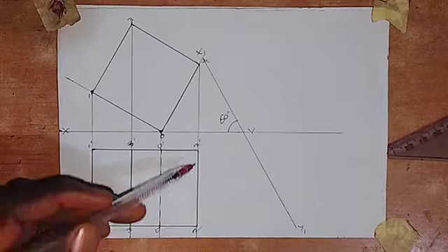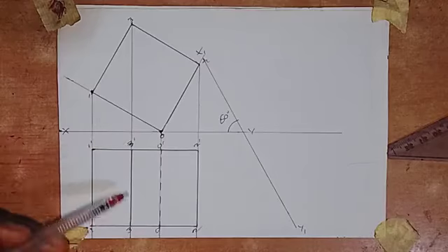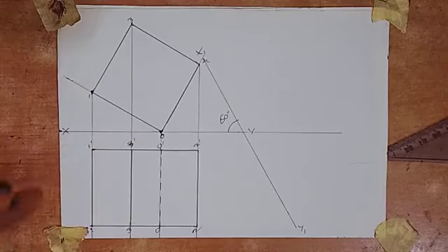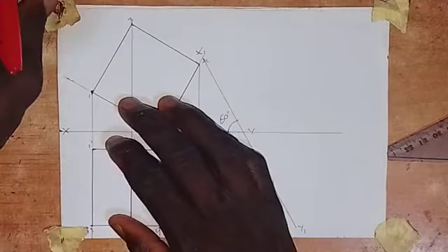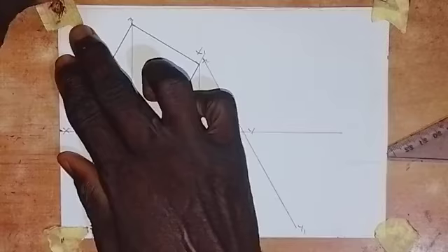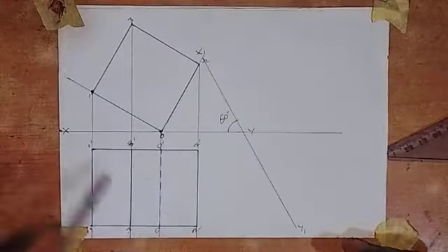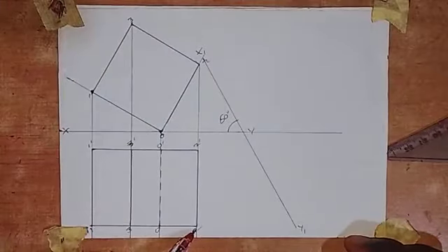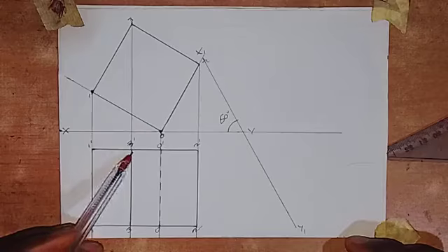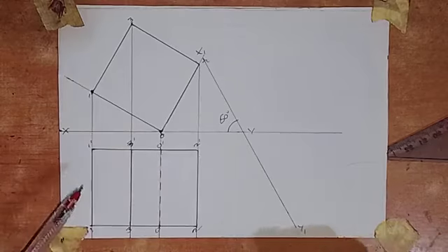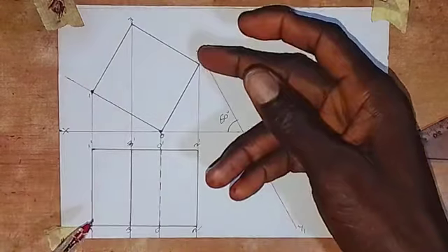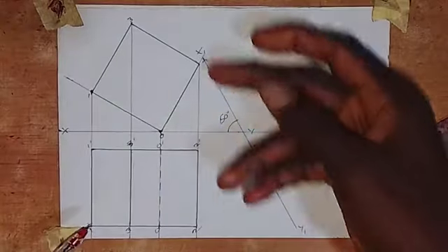Now, whenever we are to draw an auxiliary elevation, we are to project line from each point on the given plan. Whenever we are to draw auxiliary elevation, we are to project line from each point that we have on the given plan. So we are to draw a line from this point, this point, this point, this point, this point, this point, this point, and this point. And the line will be at a right angle to this line.